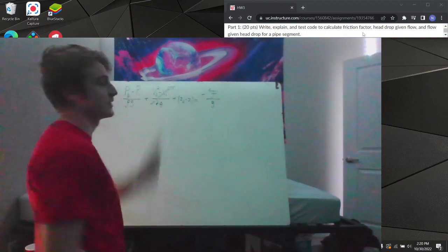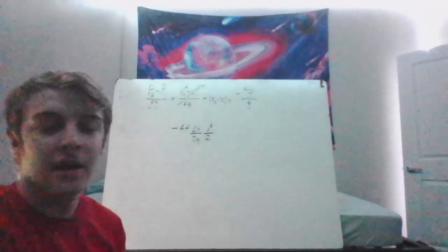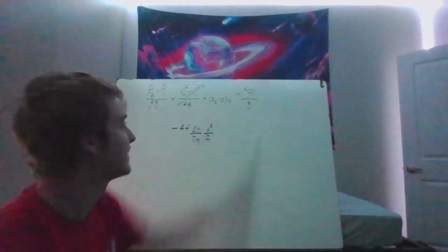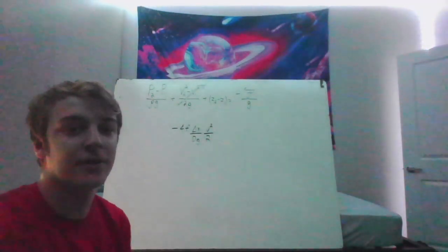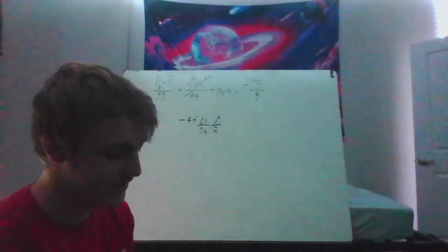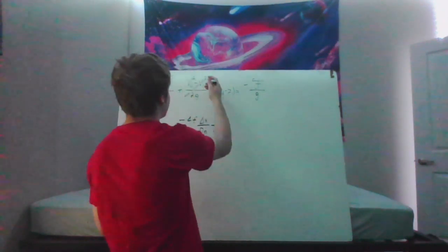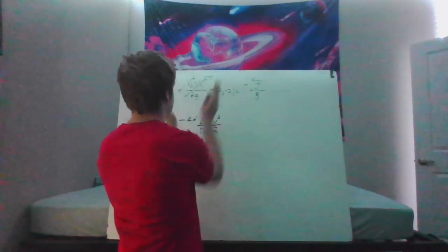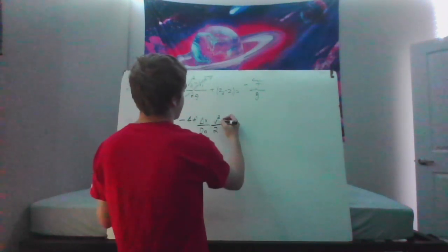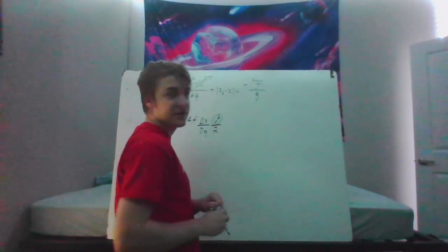So now that means that our velocity will be staying constant since our flow is staying constant. And now you can see I've written the right hand side of this equation here, and this is actually from a previous video where we calculated the fanning friction factor at laminar flow. Again, our pipe will be at a constant velocity and a constant diameter. So again, we got rid of this portion of the equation. So now you can tell that there is that velocity that we're going to have to find once we start coding.